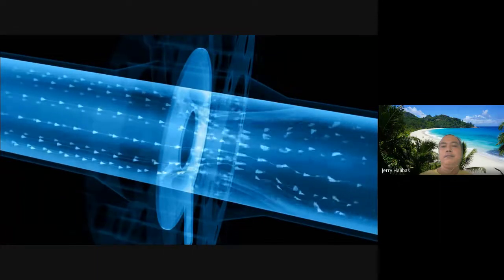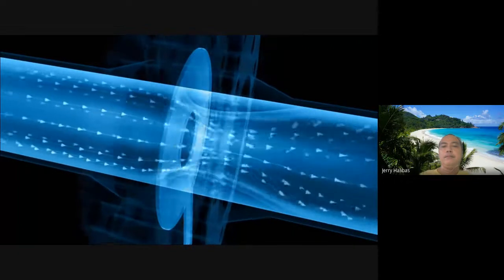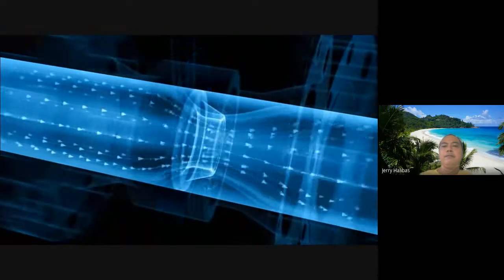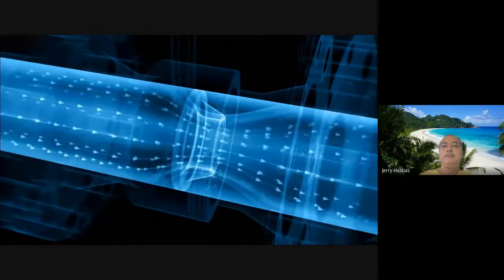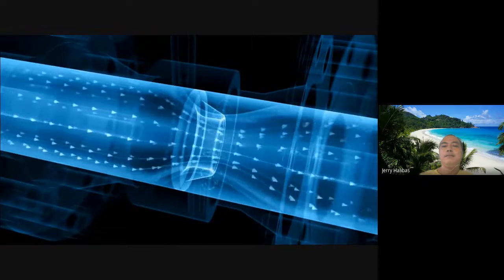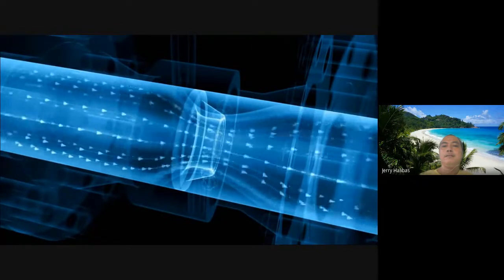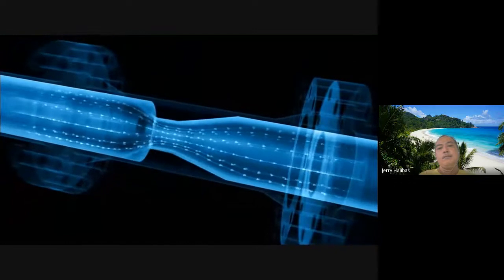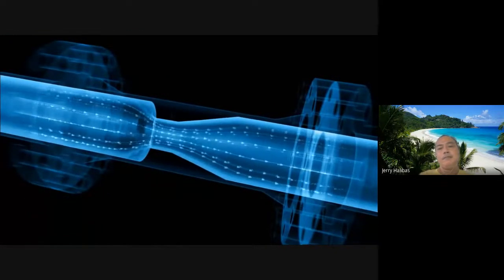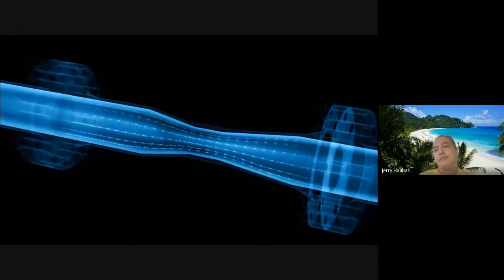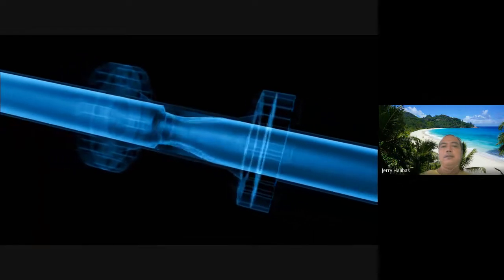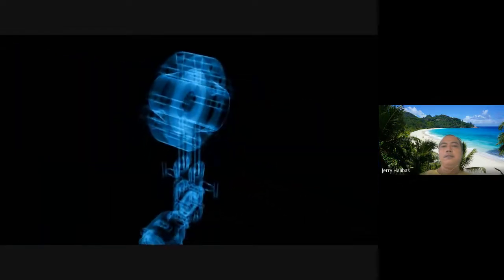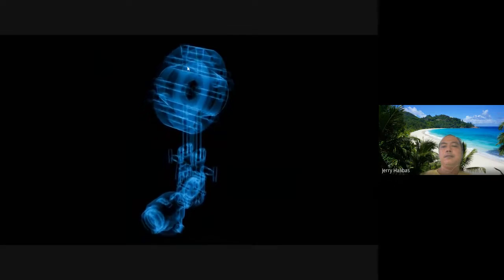This demonstration shows that an abrupt restriction generates severe turbulence in a fluid. Nozzles with a rounded, funnel-like inlet clearly reduce turbulence and thus create less pressure loss. Nozzles are particularly suitable to higher flow velocities or to fluids with abrasive solid particles. Turbulence reduction is even greater with Venturi nozzles. And finally with Venturi tubes, where the restriction is created by longer conical constrictions in the pipe wall. All these designs can be supplied with different restriction diameter sizes, so that the pressure loss and the differential pressure generated can be optimized for the process conditions.